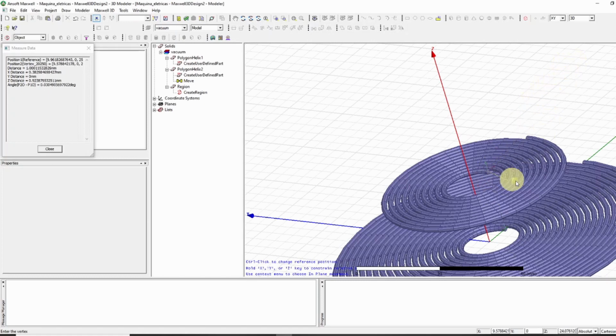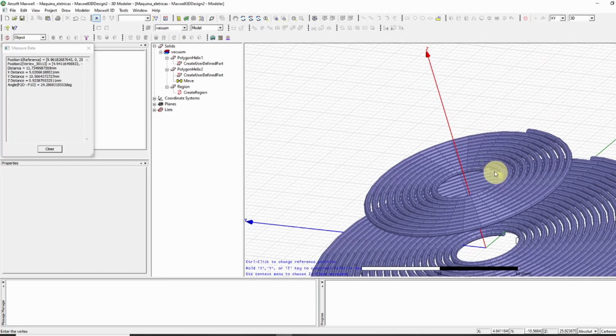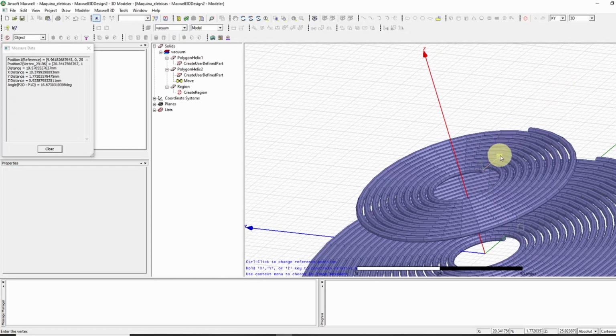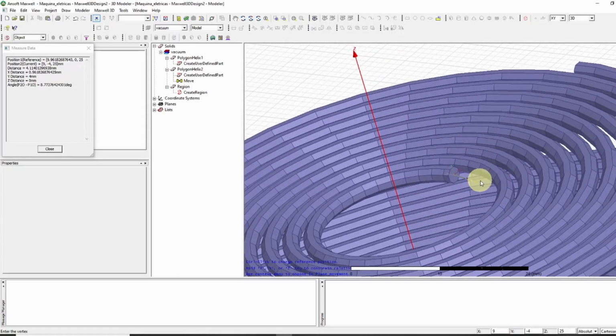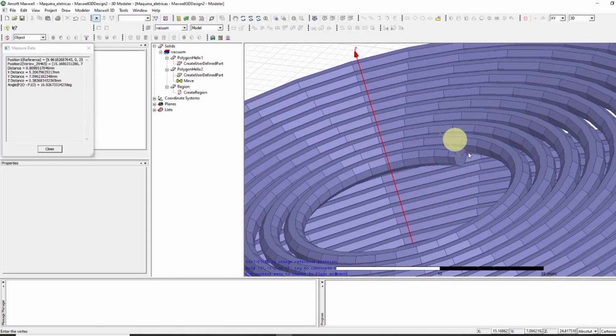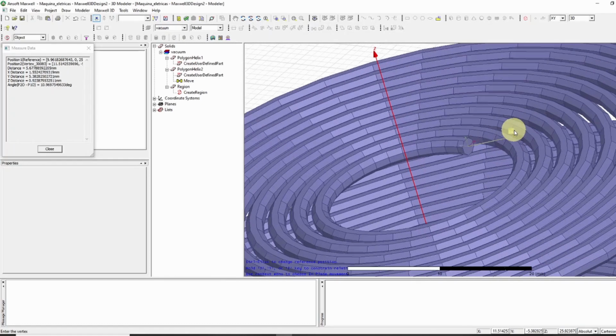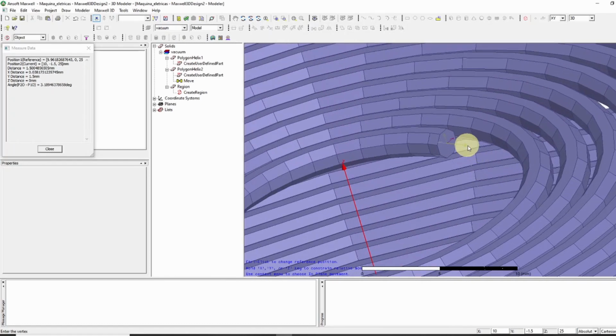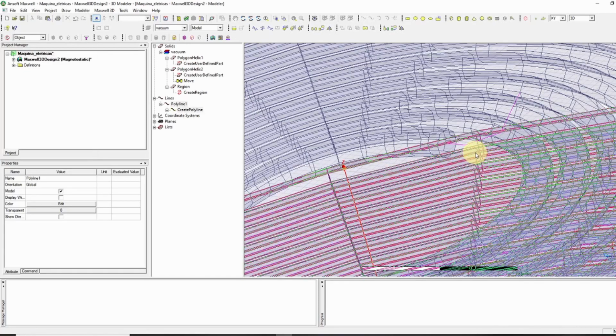I don't want to go straight to the x-axis because it's going to be weird in the design I'm creating. So I'm going a bit into the negative y direction, a bit in the z direction, then going to the x direction. It has to go through the z direction in order to go past the other coils here. Since they are in the same plane, I cannot go straight forward into the x-axis. I have to go a little bit further or below in order to go to the x-axis, naturally. So let's do it. I'm creating a line here. I'm not specifying any directions now. I'm just creating, doing 1, 2, and 3. That's all we need. So for now, we have the line created.